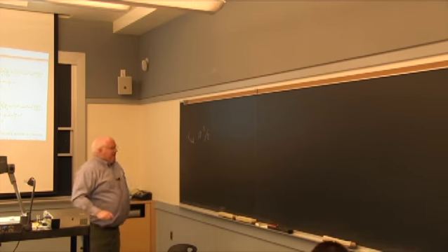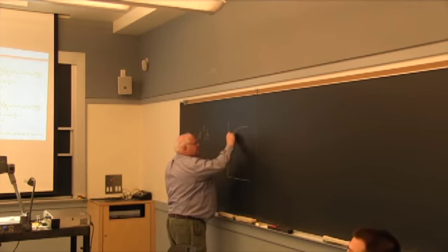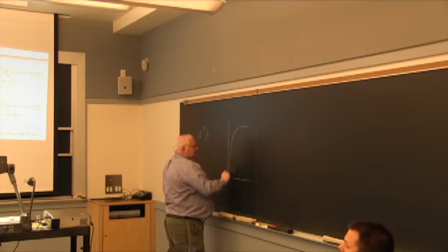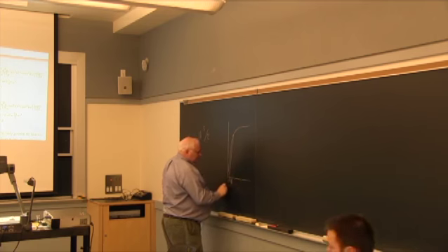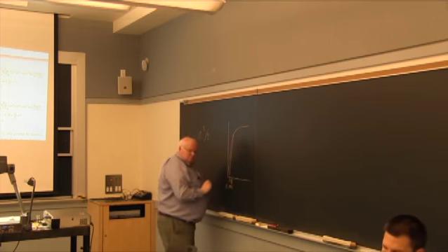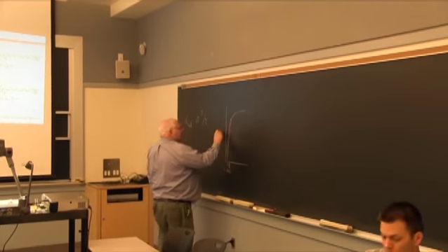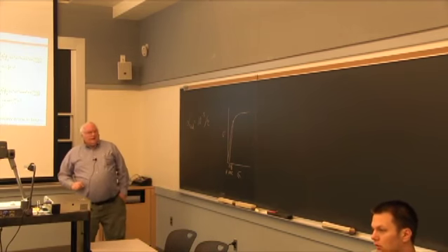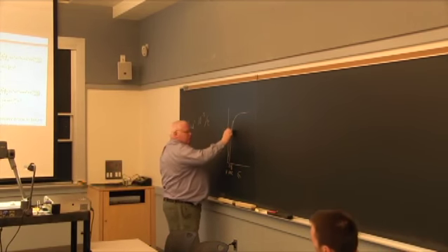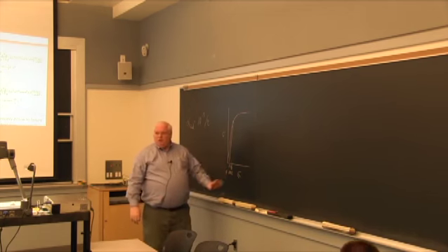0.002 strain. If you draw a stress strain curve, and this is the yield point, and they usually define the yield point at 0.2% offset, or a strain of 0.002, for a metal, for your stress strain curve. Stress, strain. They match the slopes, right? Yeah, they match the slope, so you could argue that it's 0.003 or something, right? I mean, you have to look at the modulus and stuff, but let's just take our 0.002.